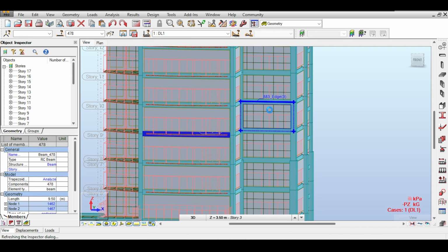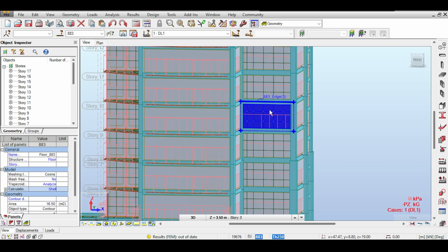As for the shear walls, this is where I personally am a little bit generous. I think that shear walls are one of the most important elements in the structure. So I am usually okay if I over-design shear walls a little bit, because it gives stability to the structure, and it really is a good investment in that case.